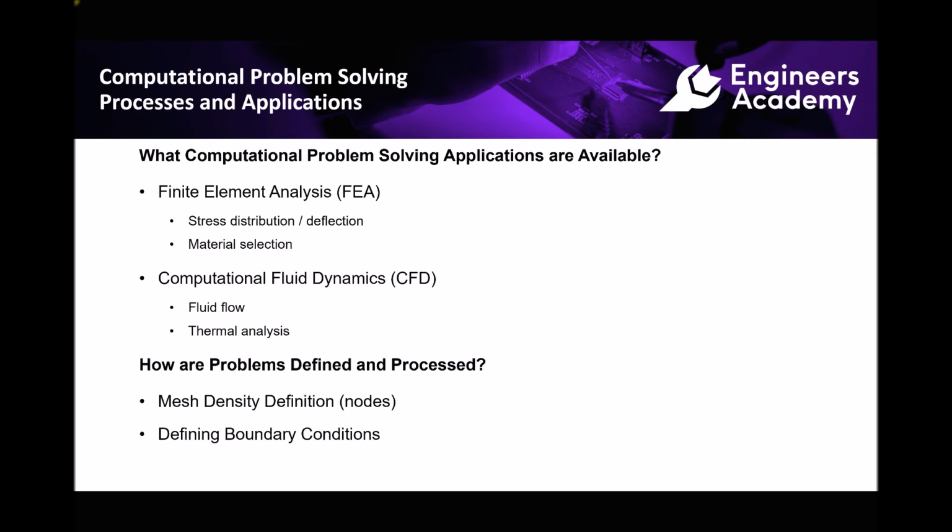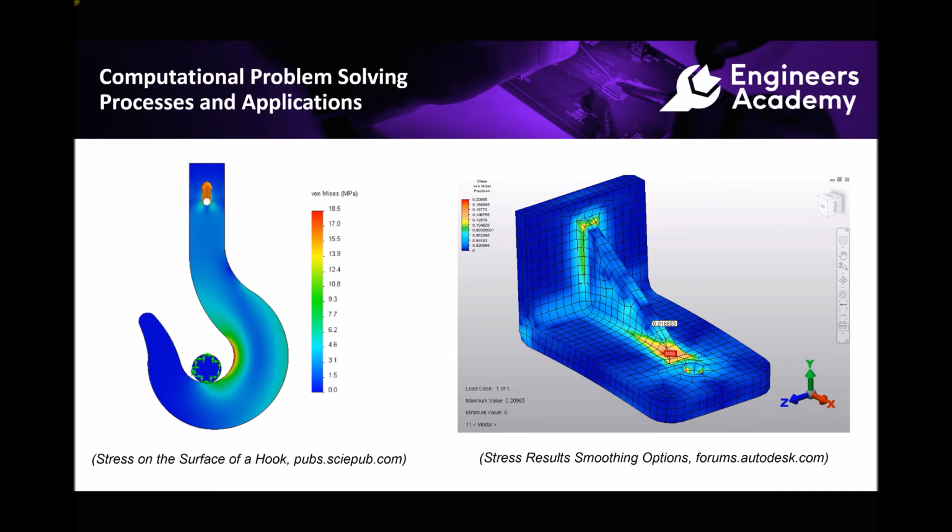So next, it's important to consider something called boundary conditions. Now, if we didn't have access to computer-aided engineering techniques, then our boundary conditions are essentially the inputs to any stress-strain calculation. We would know the force, we would know the cross-section, we would know which components were constrained. Now that's a very simplified way of considering boundary conditions, but what we have to do is tell the computational model what's fixed, where forces are applied, how mating surfaces are relating, and so on. And I'll give you a few examples of this.